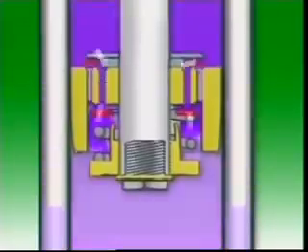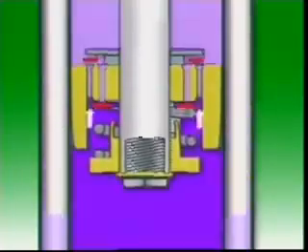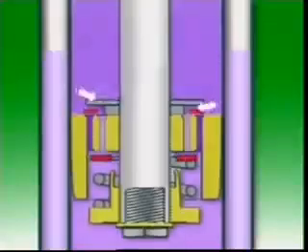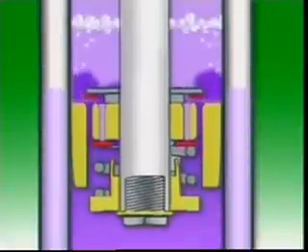Aeration occurs because of the high velocity of the oil as it passes through the small passages in the valves. If the velocity is high enough, air dissolved in the oil comes out of solution as small bubbles and forms a foam.